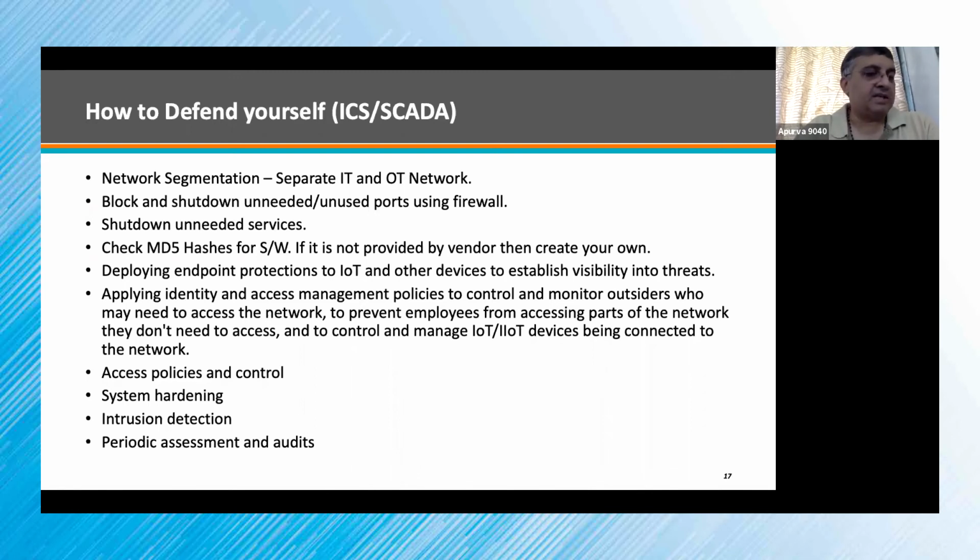I spoke about the HMI software. You can always go and ask OEMs, can you give me MD5 hashes for the software? If you have the MD5 hashes, you validate them and find out whether your software is compromised or not. If the vendor has not provided them, you need to create one and then ensure that it always matches the hash you have created. That is the most important point to remember on the software side of it.